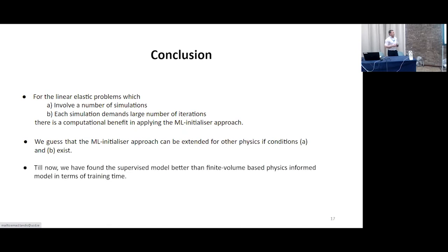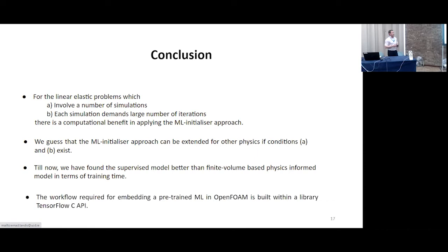And the physics-informed approach was not really beneficial here because it required much more time. We thought that because we don't need prior solutions, it would be faster, but actually the overhead time is much more, and we cannot justify it until now. And at the end, we have built a workflow for applying a machine learning model within OpenFOAM, and it can be used for other purposes.